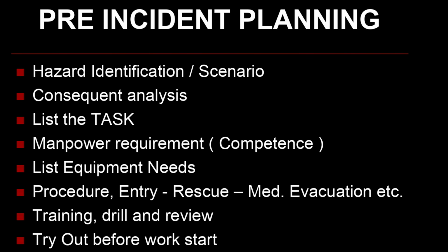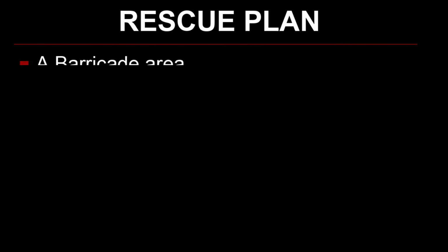Pre-incident planning. 1. Hazard identification scenario. 2. Consequence analysis. 3. List the tasks. 4. Manpower requirement, competence. 5. List equipment needs. 6. Procedure: entry, rescue, medical, evacuation, etc. 7. Training, drill and review. 8. Try out before work starts.